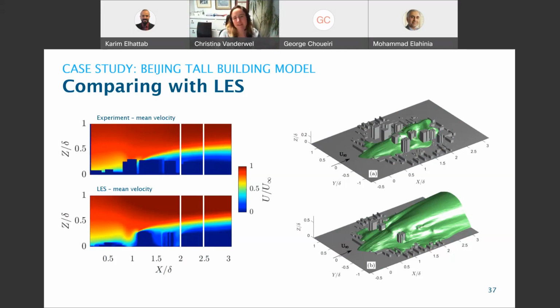So that lets us do this rendering on the right-hand side of the isocontours of the concentration. And we can see that it is released upstream from this point and seems to stick quite close to the ground until we impact the first tall building, and essentially has a chimney effect and is really shooting that pollution out into the upper atmosphere. I think LES is quite remarkable that you can do these sort of renderings with them.